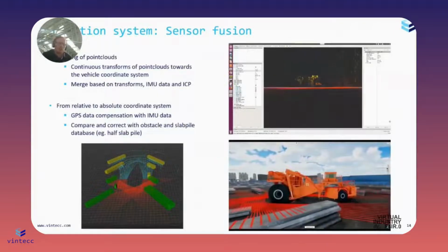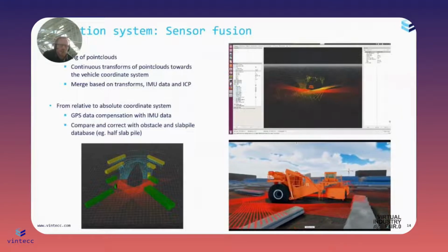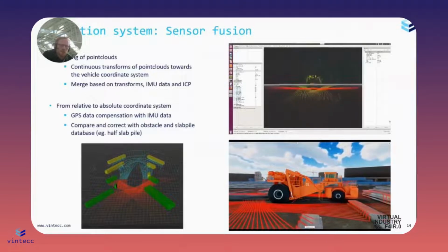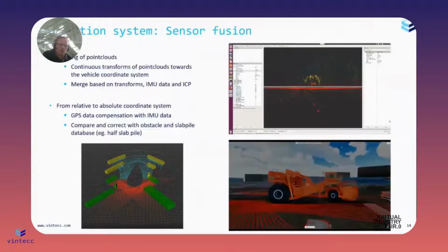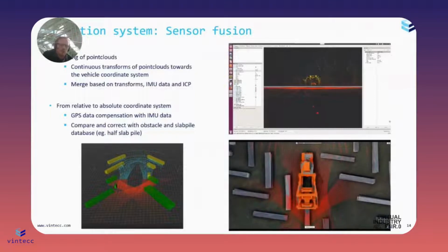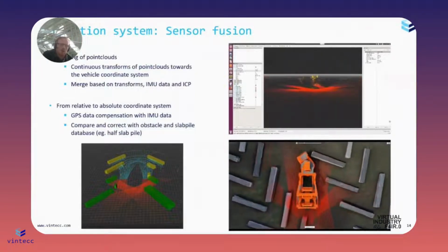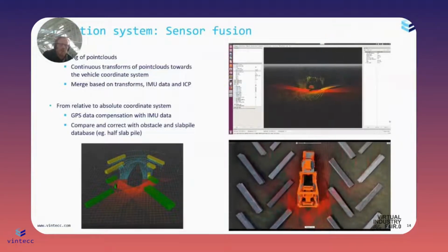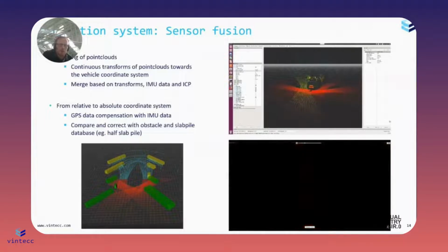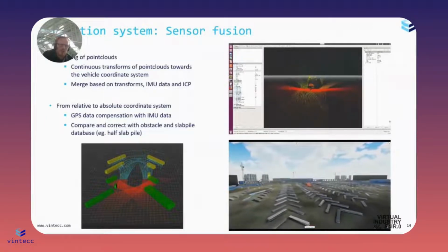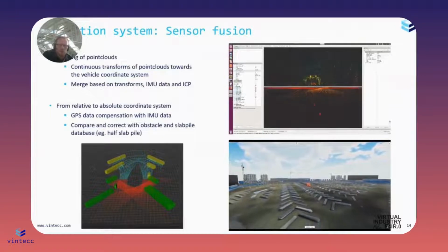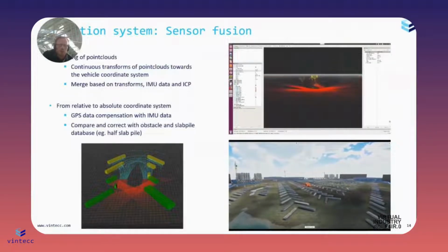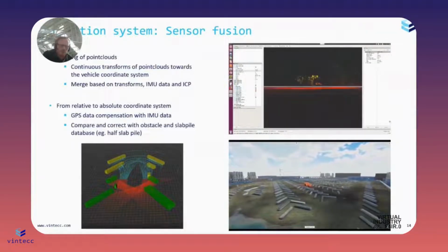We of course have an initial setup that we try, but then we search for small deviations, for example supports that are a little bit different. Sometimes, with hot and cold over such a big machine, it can differ in the image by a few centimeters in the LiDAR point cloud. So we need to stitch everything together. Therefore, we also need IMU data. We need to do some fusion with the IMU data, and we need some ICP algorithms there.